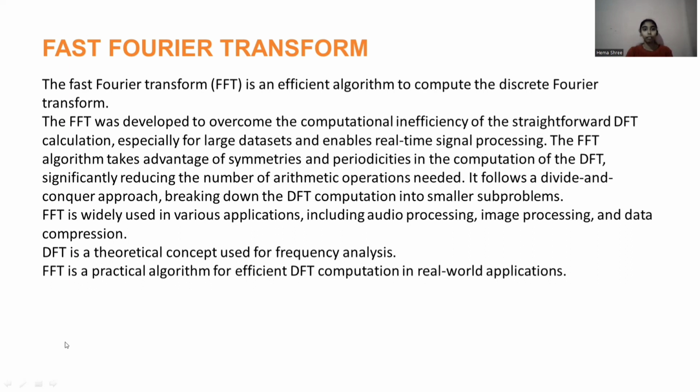Fast Fourier transform. FFT is an efficient algorithm to compute the discrete Fourier transform. The FFT was developed to overcome the computational inefficiency of straightforward DFT calculation, especially for large data sets, and enables real-time signal processing. The FFT algorithm takes advantage of symmetry and periodicity in the computation of the DFT, significantly reducing the number of operations needed. It follows a divide and conquer approach, breaking down the DFT computation into similar subproblems.